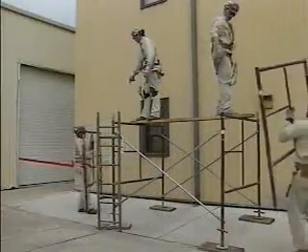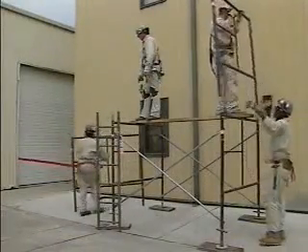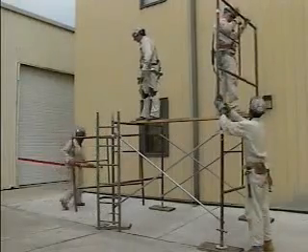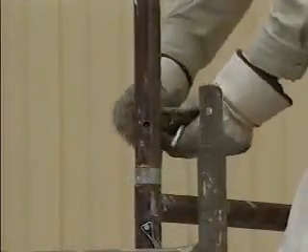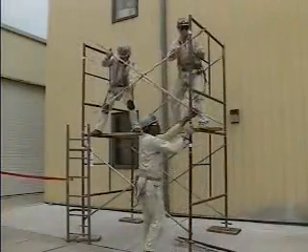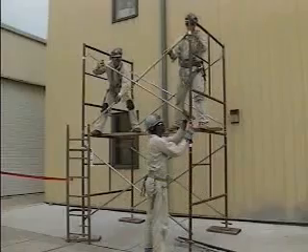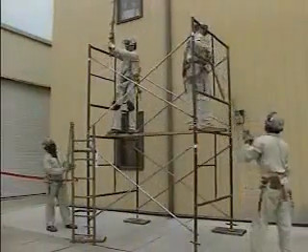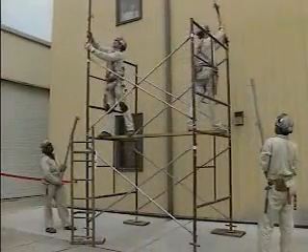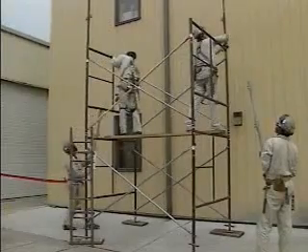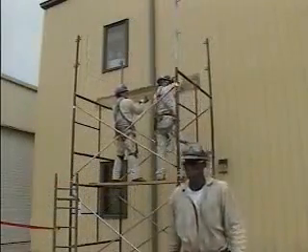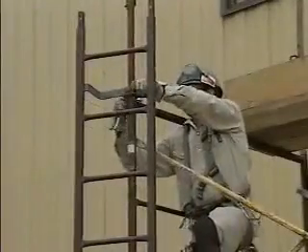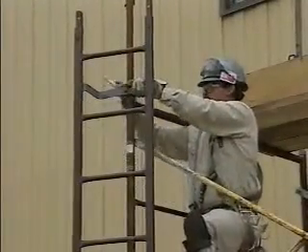The assembly procedure is basically repeated at this point. Two more vertical end frames are placed onto coupling pins in the lower end frames, and each frame leg is secured with a locking pin. Then cross braces are added to stabilize the upper end frames. The next step is to insert vertical guardrail posts into the tops of the upper end frames. Then scaffold planks are added to create the work platform, and another section of ladder is attached.